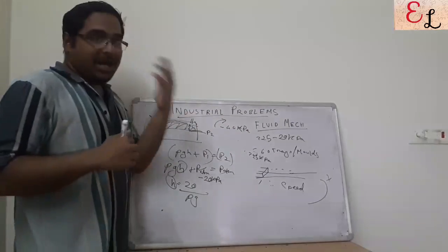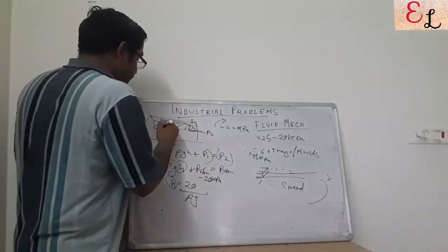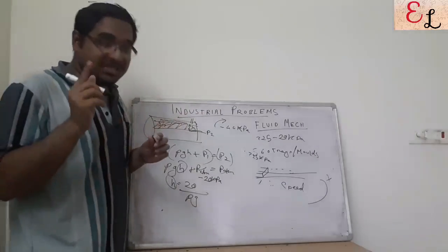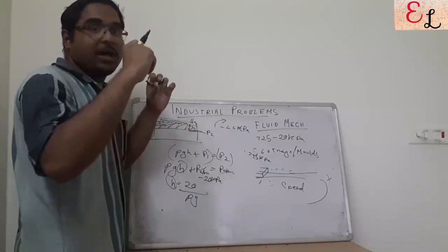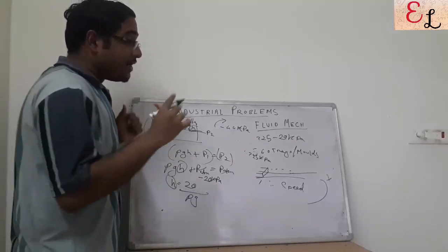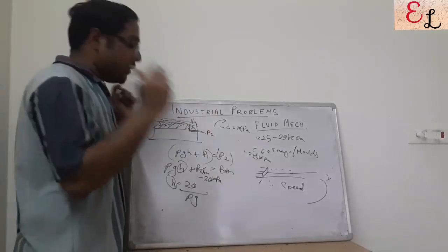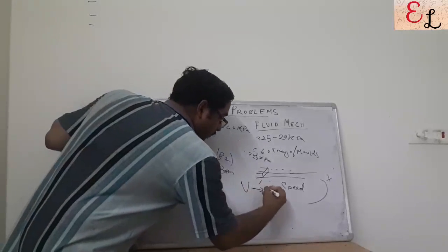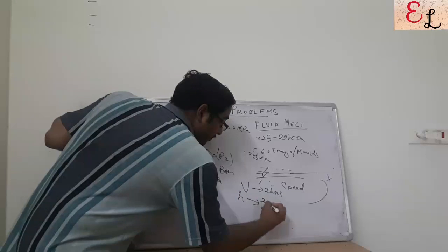After 2 hours, we know the amount of slag that is formed, the volume of the slag that is formed. Once we know the volume of the slag that is formed, by going with the geometry of the horizontal cylinder, we can find out the height it corresponds to. If this much volume of slag is forming in 2 hours, we will find the height of the bed after 2 hours.